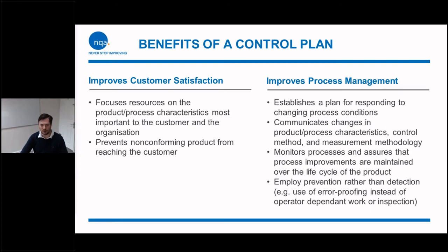Some people might have heard of dock to stock as a process where products come in from the suppliers, they don't even open the box, they go straight either into stock or straight to the line, you know, just in time feeds, things like that. So a lot of them will ask for control plans at least to be produced by the suppliers for those specific parts, which then gives them confidence when the parts are coming in that they should be meeting the requirements. So as long as you're following the control plan, and it will be done per part, it's not an overall risk thing.